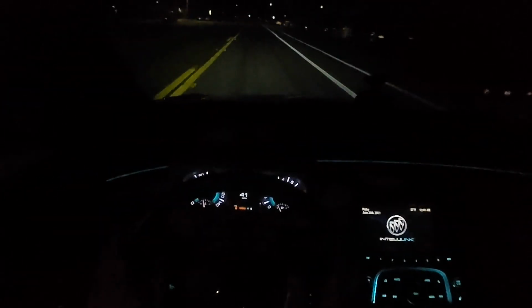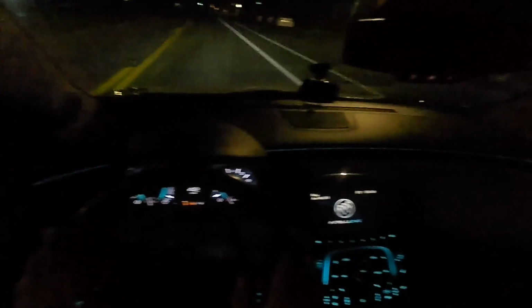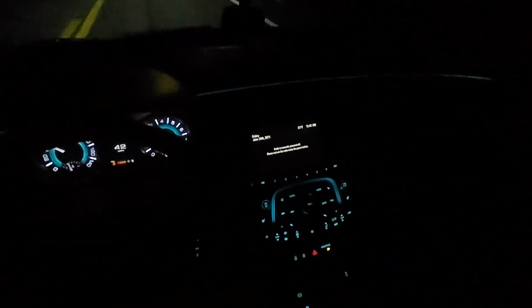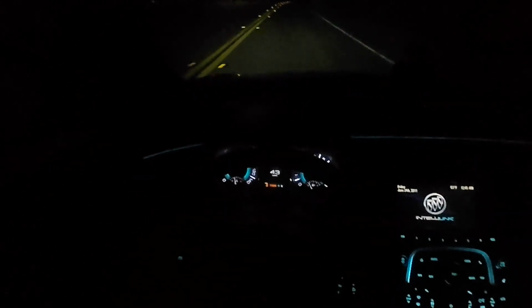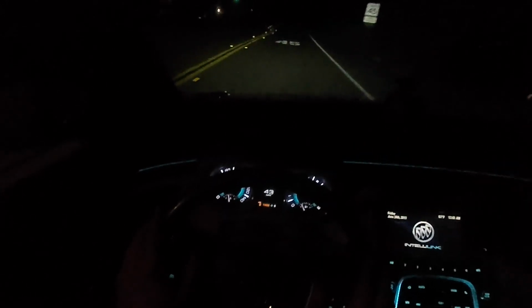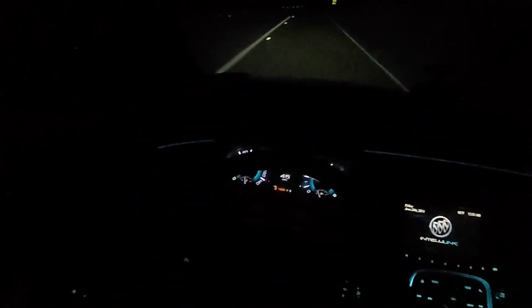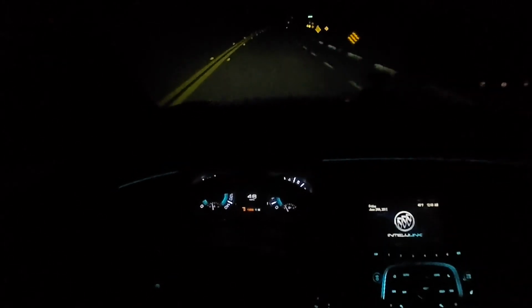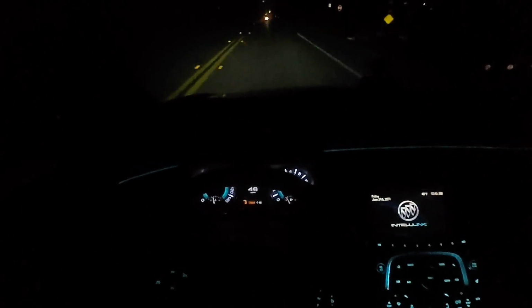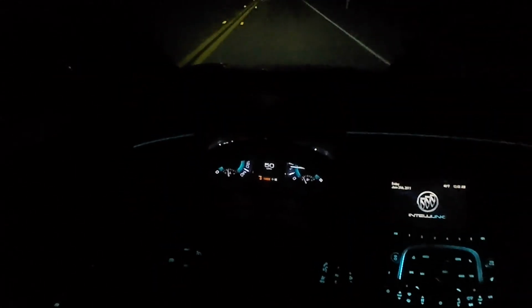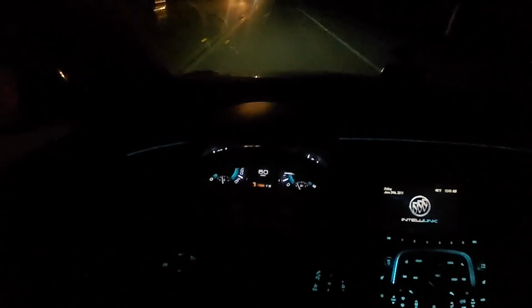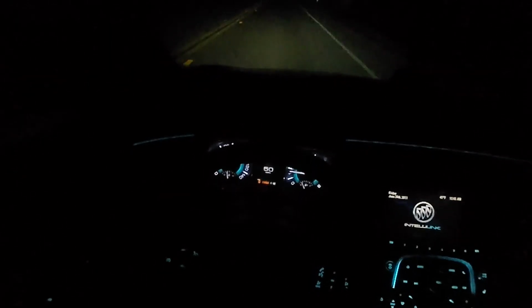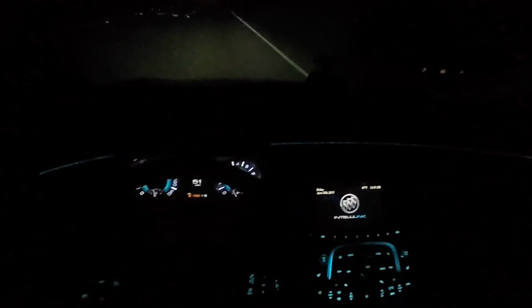And right now I've been driving it smooth, trying to let the ECU learn the values, and the traction and the sensing on the system, as we did reset the ECU by taking out the battery leads. And now I'm gonna go again on the highway and drive it a little bit more, but as far as I can tell for now, I believe I was able to resolve the issue and the car is back on track. No code and no StabiliTrak issue.